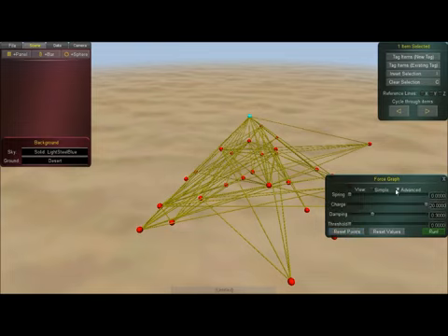If we go to the advanced mode, then what we're going to do this time is individually set, if you like, how much spring in it and how much charge we've got. So let's start them fairly equal. Damping and threshold. Damping is basically how quickly it uses up energy. So what we tend to do is set that right to the left hand side, which ironically means it uses up the least energy, so you get the most change as the system runs. Threshold is so we can get it to automatically stop once a certain movement level has dropped to, but we tend to find it's easier just to control it manually.